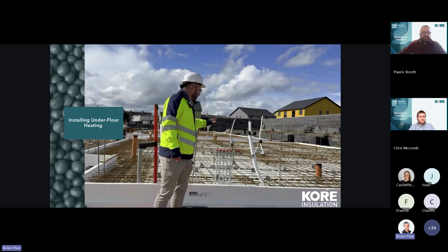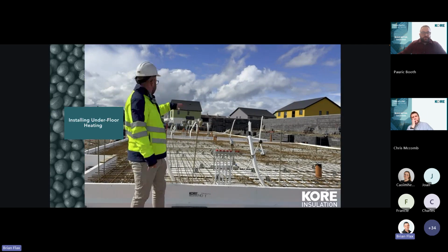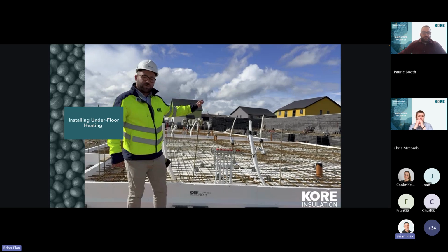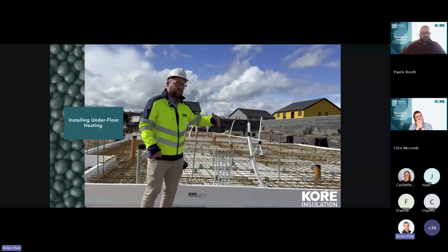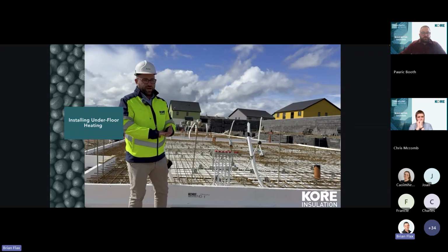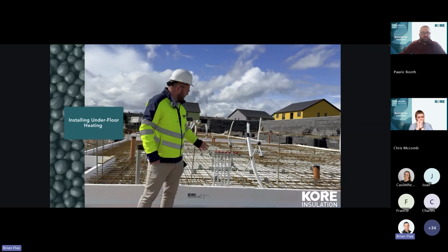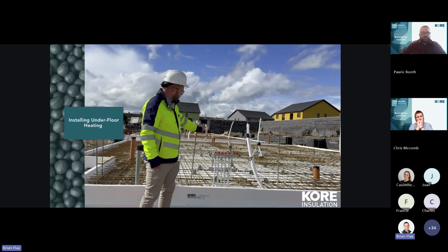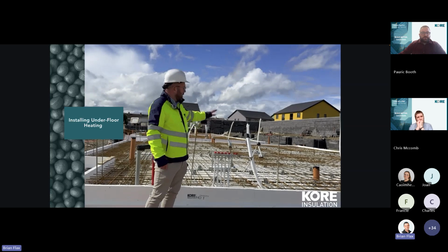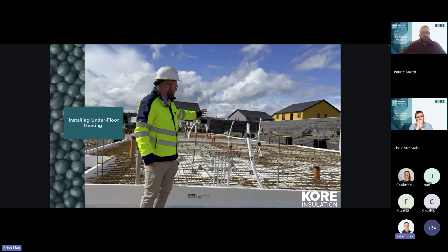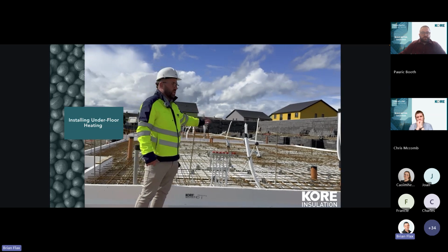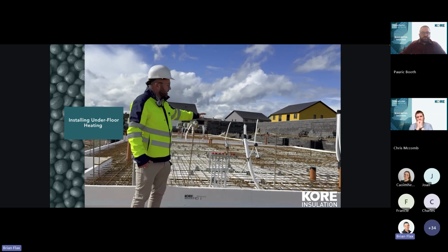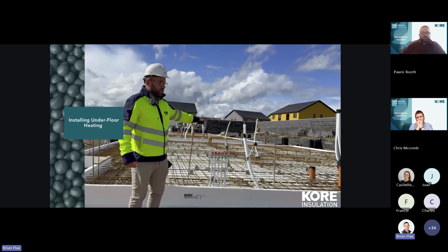Right, so here we have an L profile foundation. This is again a semi-detached unit being used for ICF, with start bars coming up. But it can also be used for timber frame with external insulation and external cladding. What you can see here is the underfloor heating pipes installed on top of the final layer of the EPS 100, so that's 150 mil below the concrete. There are different methods to install the underfloor heating. This is one of the recommended ways to do it.